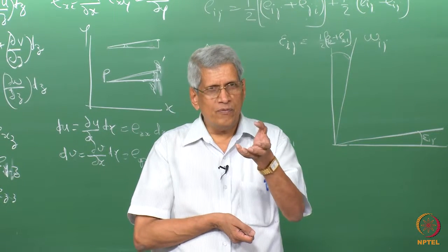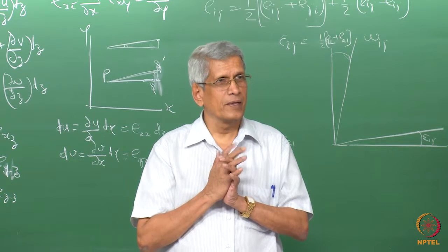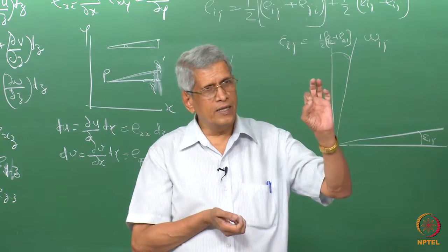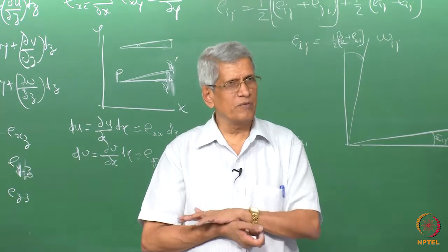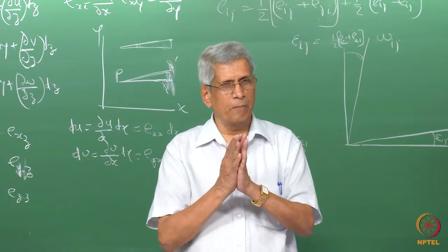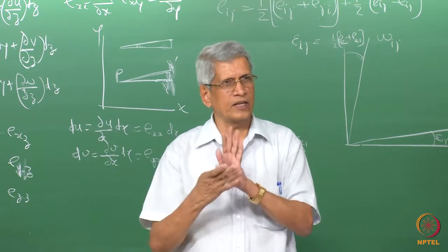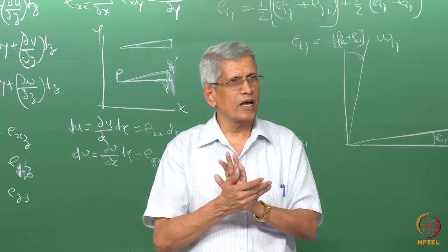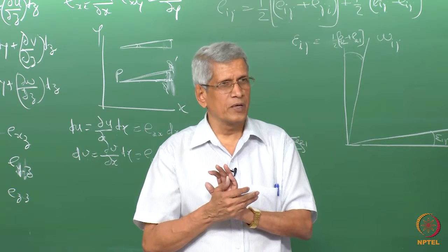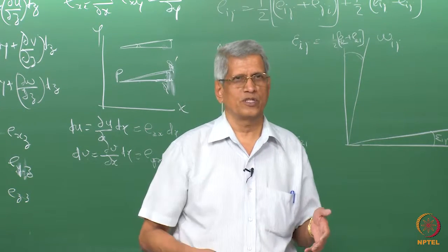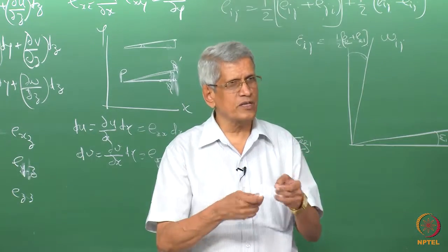That is, when we look at the deformation of a polycrystalline material, at the middle of the grain mostly strains will be there. Closer to the grain boundary, when the matching between the boundaries has to be maintained, and suppose the boundary on the other side is very hard, the only way it can accommodate is by just a rigid body rotation. But rigid body rotation is also equivalent to a strain. With respect to whether the material has really undergone a strain, no, correct?